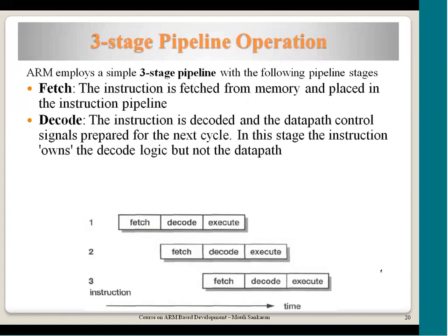Now decode is understanding the instruction based on the format of the instruction. I told you about the 3 parameter or 3 operand format, and then there is a functional code which also tells what operation the particular instruction is expecting from the processor to be performed. So that information is decoded.